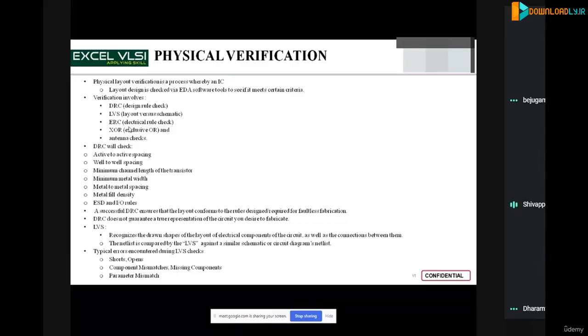Now, when you are performing static timing analysis for a combinatorial circuit, what does it mean? You are giving inputs and getting outputs, and the outputs come after the delay of the combinatorial circuit. To give an example, you have a 2 input AND gate. The AND gate propagation delay is, let us say, 2 nanoseconds.